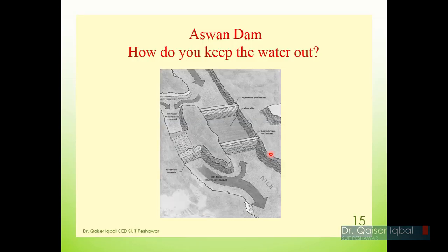Okay, so there were a number of applications of soil mechanics in this dam, and any other rock fill dam will have a number of applications. For example, they first diverted the flow over here to a temporary canal through coffer dams. You can see the upstream coffer dam and the downstream coffer dam. A coffer dam is also an embankment. It's material which we bring and dump over here so we can have a dry working area, because they wanted to build the dam starting from here to here.